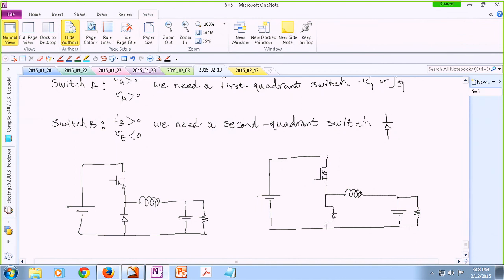So this is still going to give you a buck converter. And remember, MOSFETs always come with a diode. So this is always there. But we never use it because the current never changes its direction. And in the bottom, you also have a MOSFET that you may or may not use. Let me see if I can make this a little bit thinner.